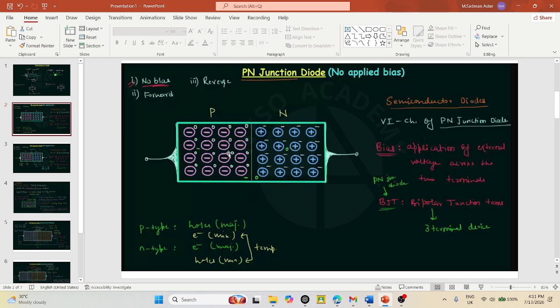Now we will be discussing about the p-n junction. In p-n junction, a p-type semiconductor is connected to an n-type semiconductor. In p-type semiconductor, we dope the semiconductor with trivalent impurities. These impurities or materials have one less electron to fill its octet in the outermost shell, and they always try to accept one electron. So this type of materials are acceptor materials.